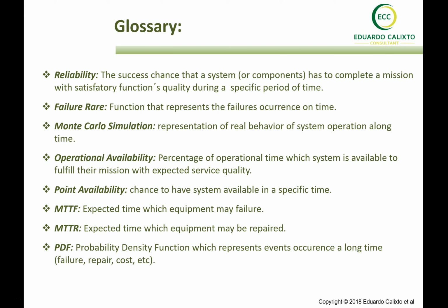So these three issues define the reliability and, of course, cause effect on reliability. Failure rate is the function that represents the failure occurrence in time. As we will be demonstrating and discussing during the lifetime data analysis module, we can have constant failure rates, or increased failure rates, or a combination. Many engineers believe the failure rate is always constant, and they apply such a concept for all equipment, and that's totally wrong. We are discussing that in the module lifetime data analysis.